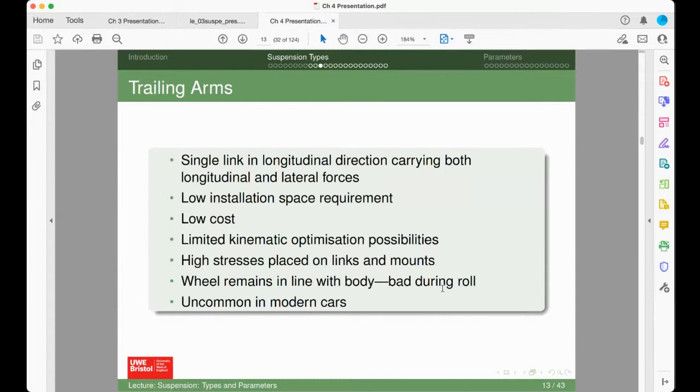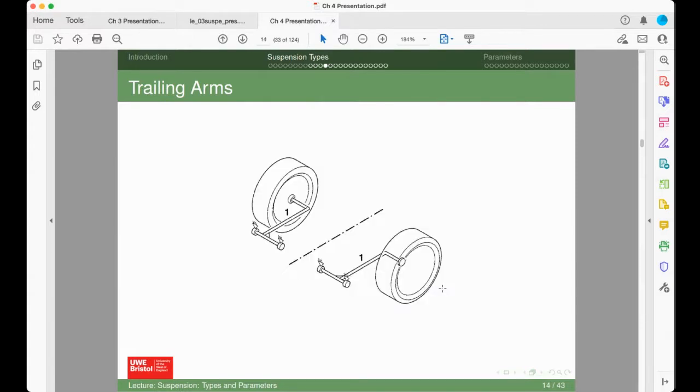A car that you may be aware of, again, it's before your time generally, but the Citroen 2CV had a trailing arm suspension, both front and rear, and in the front it was not actually trailing, it was leading, but it's the same sort of setup basically, where you've got a link between the body and the wheel that was an arm that moves up and down. So a schematic of a trailing arm looks something like this, and you can see that it's a very straightforward, simple setup.